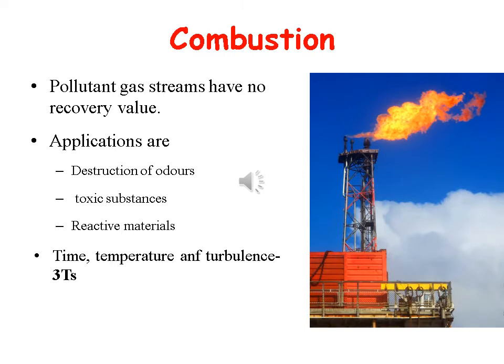The next method of air pollution control technique is combustion, used where the pollutant gas streams have no recovery value. So absorption and adsorption methods are not feasible, so we are adopting the combustion method. If the waste gas contains sufficient combustible material, then incineration may be adopted to control air pollution.